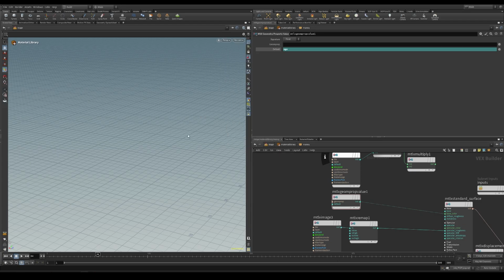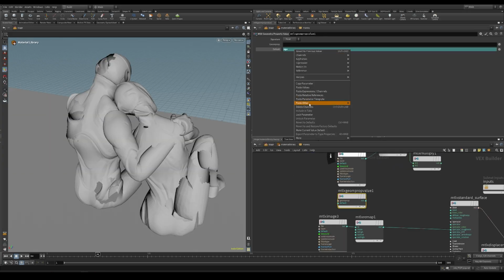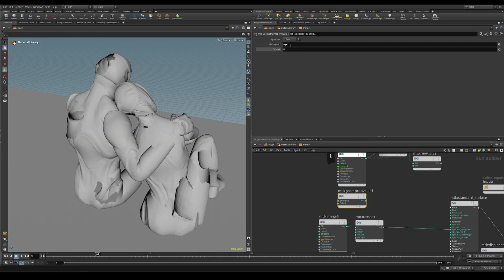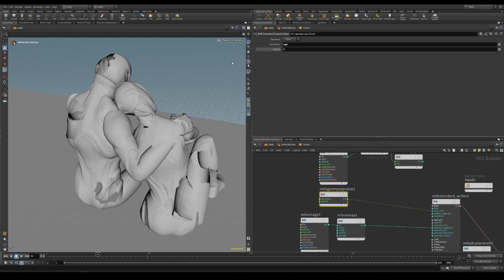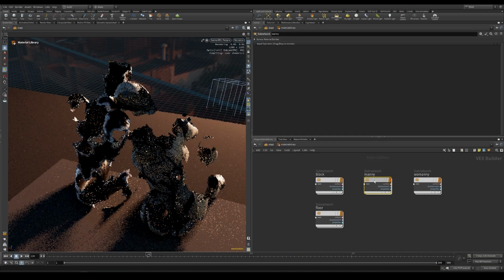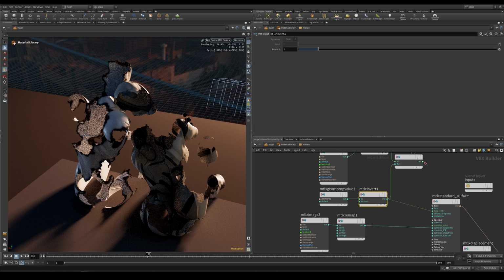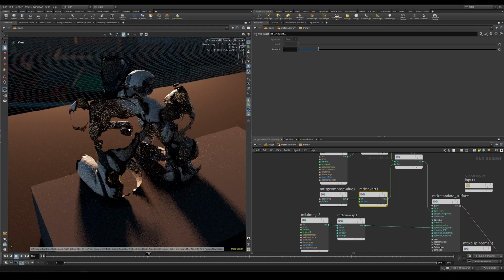Reset Karma. Where is everything? Put it into the default. Here we need to plug edge. So base color, and we should see something. And let's go back here, or we can't see the materials. Yeah, we are multiplying the edge color. So invert it, and this will be multiplied by the current base color. So something like this. And maybe, I mean, yeah, the full amount is fine, whatever.